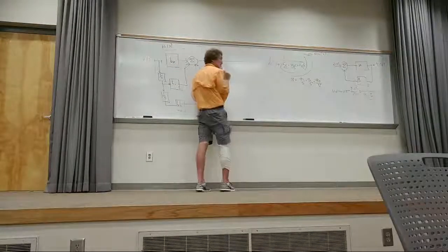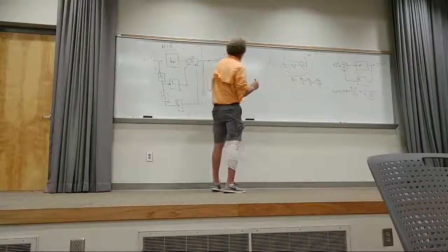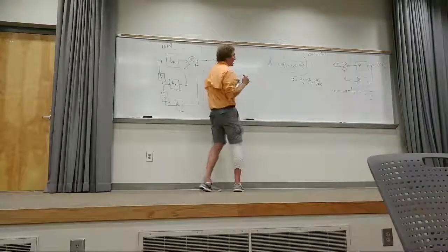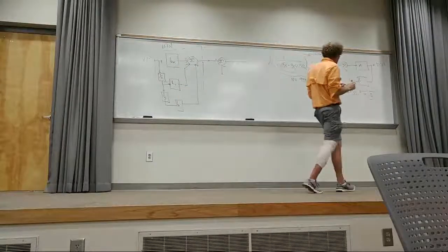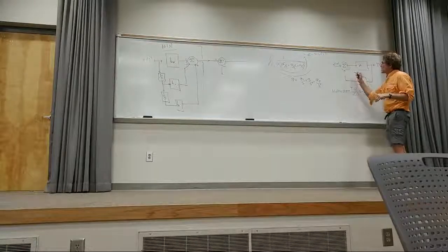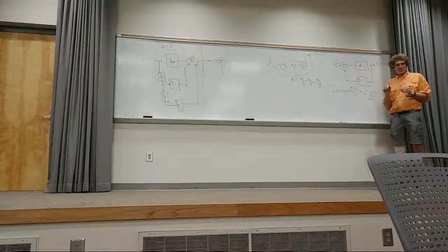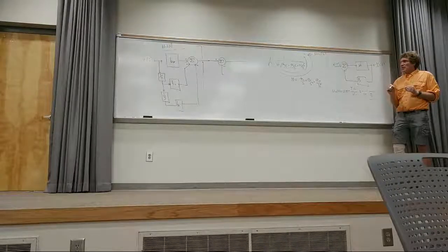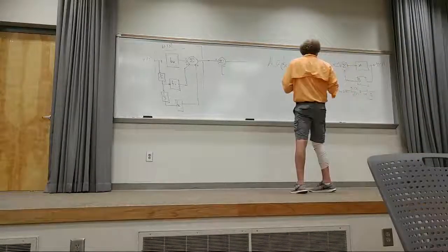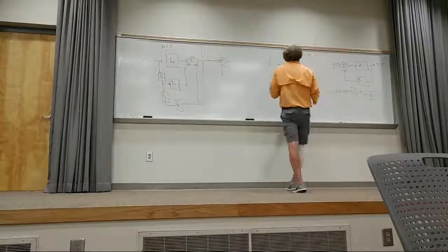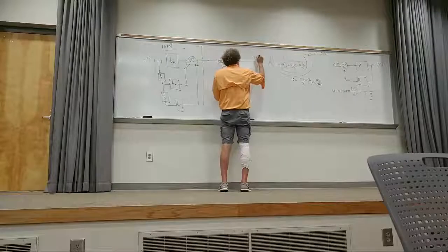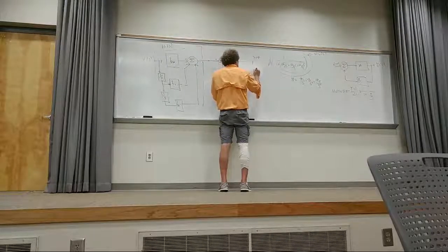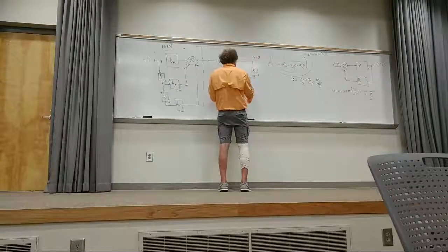My reverse gain is all of that: A1 over S plus A2 over S squared plus A3 over S cubed. And all that's being fed back here as a negative. That's a negative sign, isn't it, class? Are you with me? So follow me how I do it. I take the output, which is Y of S now, the complete output. I put a block that has 1 over S here, and then I multiply it by A1.